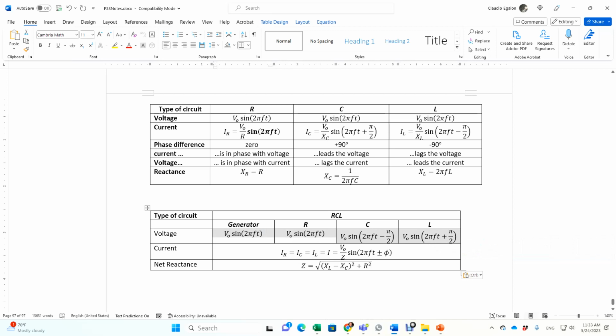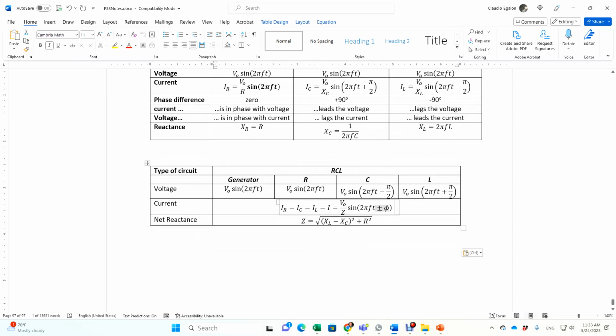But now the current is going to be out of phase with the voltage by an angle phi, given by that relation I showed to you before. The net reactance ends up being this equation. That's the term that tells you how you tune your primary circuit. I just wrote that in terms of the reactance instead of the omega.